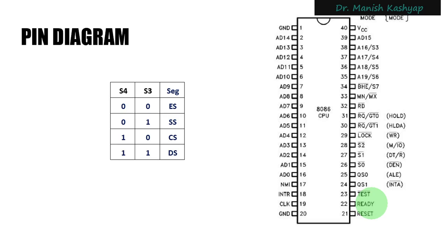What happens is, if this READY pin is high, you have to supply an input signal at it. This pin is definitely treated as an input pin to the microprocessor. If you put a high value at this pin, it indicates that the externally interfaced device or memory is ready to transfer the data, because there may be some devices which are slower than this microprocessor.